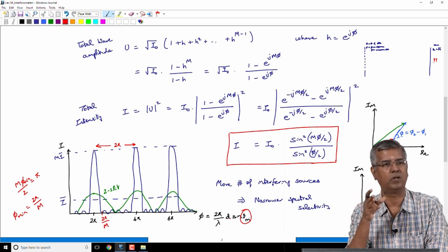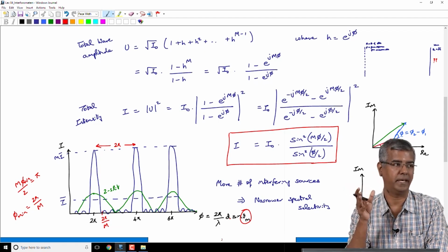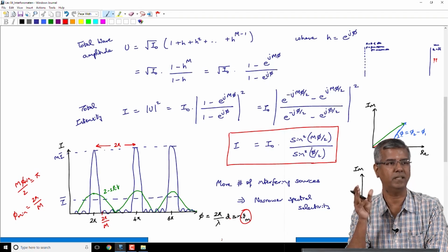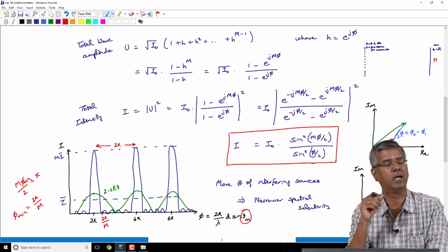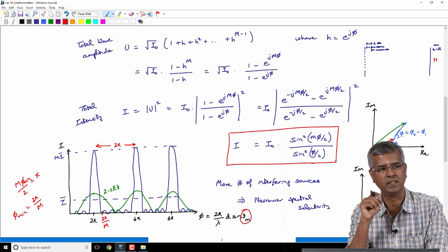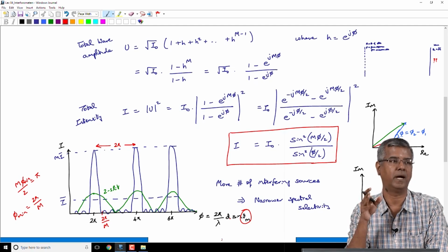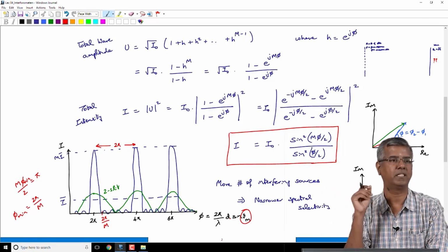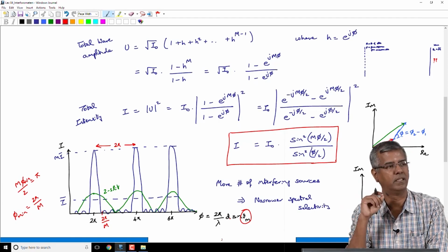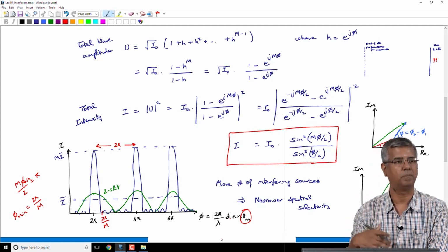and that is similar to the concept that you might have encountered in antennas. You have something called phased array antennas. Have you heard of that, phased array antennas? By manipulating the phase and the amplitude of each of those sub antennas, you can actually have a very specific radiation pattern. In fact, you have a radiation pattern that can scan across different directions just by manipulating the relative phase between the different antenna elements. So, similar concepts can be possible here as well.